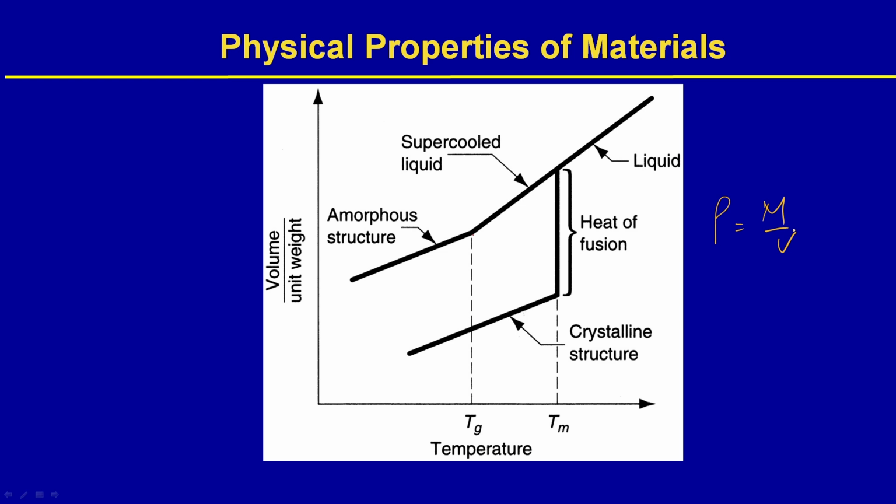So, crystals have higher density compared to glass, because crystals are more packed structures. We have discussed it. Glasses are random, so they have more open structures. Therefore, the density of glass is lower than the density of crystals. So, mass is the same, that means volume should change, right? For crystals, volume is smaller, that is why they have a higher density. For amorphous structure, volume is higher, there is more free space.